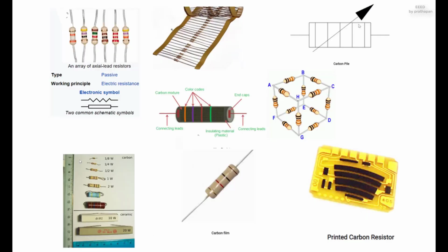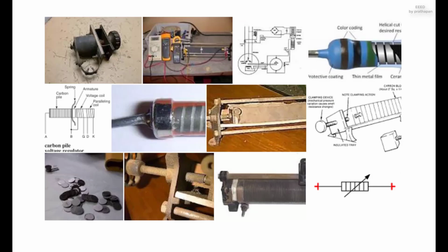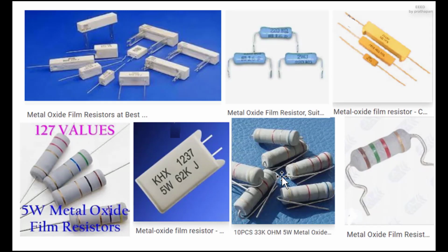A resistor is a passive 2-terminal electrical component that implements electrical resistance as a circuit element. In electronic circuits, resistors are used to reduce current flow, adjust signal levels, divide voltages, bias active elements, and terminate transmission lines, among other uses. High-power resistors that can dissipate many watts of electrical power as heat may be used as part of motor controls, in power distribution systems, or as test loads for generators.